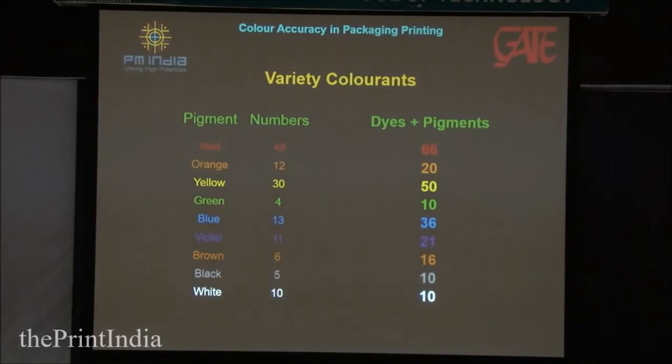Therefore, your color matching is very important, because many CMYKs are also made out of this. There is no pure cyan pigment or no pure magenta pigment and so on. Okay, it's a combination. So when you use this, therefore you need to check the color of your ink, what you get, very religiously. Yeah, you must make sure you are getting the right one, because when they process it at their factory, as I said earlier, when the temperature shifts, the color shifts. Okay.